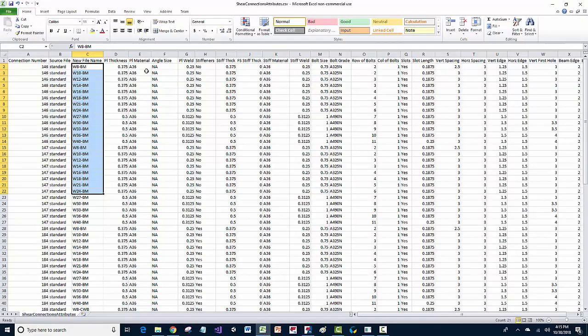All right, so everything else is pretty self-explanatory. There's the shear plate connection material grade as well as thickness. Then there's saying whether or not you want a far side stiffener or stiffeners involved. Oftentimes in beam to beam connections it's not, but if you do want that on, like a far side full depth stiffener, you can switch that to on, and then you can just enter in the thickness values as well as the weld.